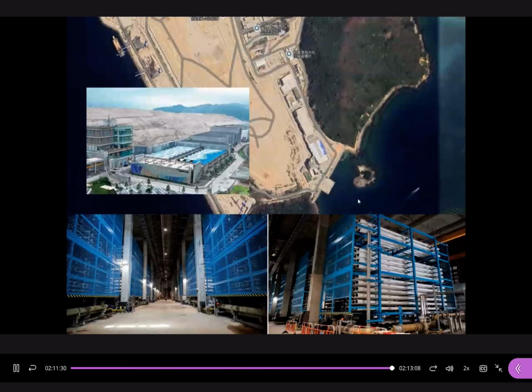We do not have a lot of calculations for this part because the calculations could be very complicated when you look at the microscale transport phenomena. So we have only a very simple, high-level understanding of membrane separation. For this part, you have to know a lot of concepts. Different types of membrane separation is a must: micro, ultra, nano, RO. What are the features, and what can we use them for? And some basic concepts like concentration polarization, fouling, backwashing, recovery yield, rejection, permeability. Different types of foulants, and what methods can we use to clean different types of foulants. A lot of concepts for today's lecture.